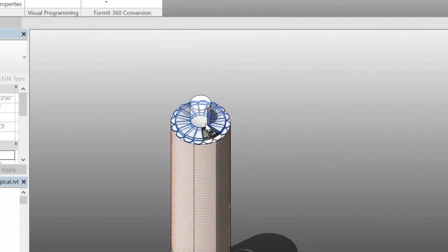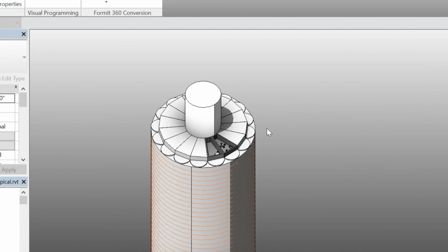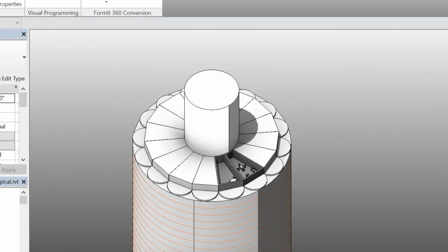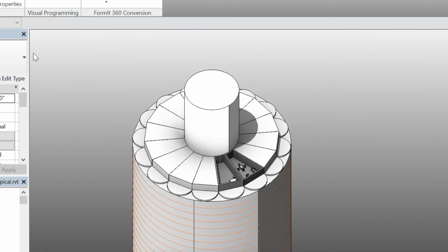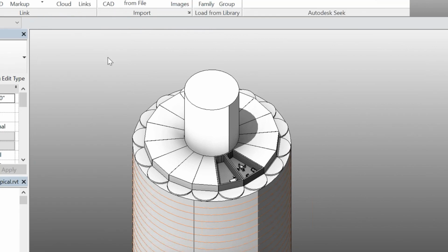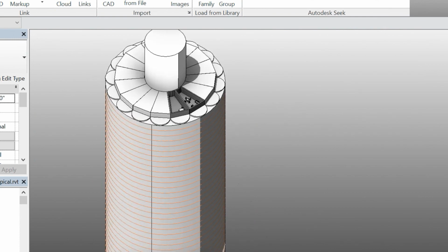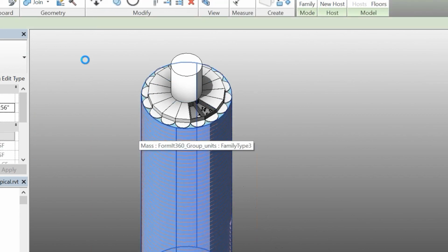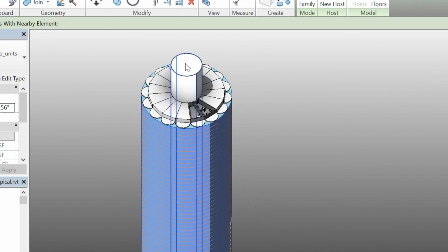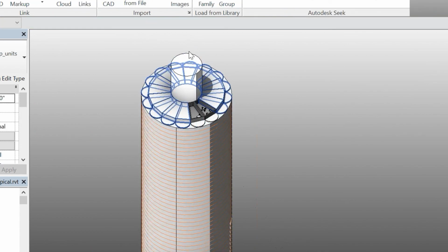The other good thing that's distinct from other competitors is, well, first of all, most of you already know, it's something we hear about in almost every office we visit. If you just go up to Revit and do insert CAD and then choose SketchUp, you're just going to get a big blob that you can't do anything with. But this entire Revit file created from FormIt instead is segmented like I described. So we've got this cylinder as a Revit mass with all the mass floors applied. This core, which I didn't have levels applied to, does not have mass floors.